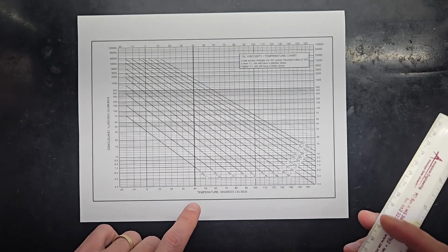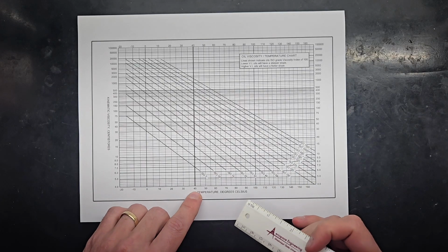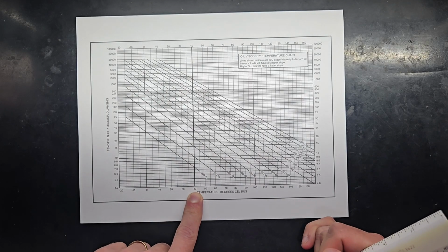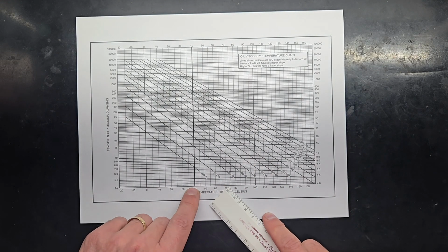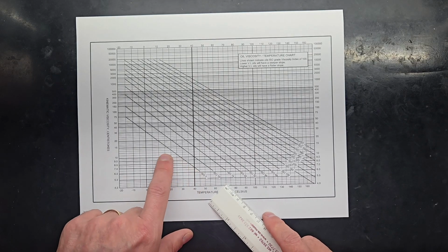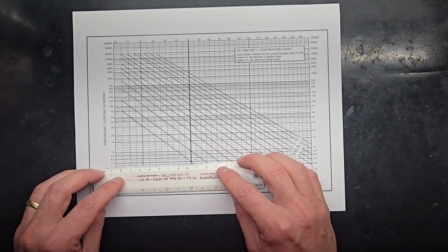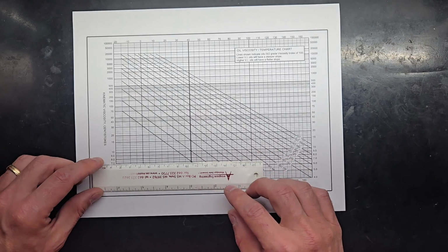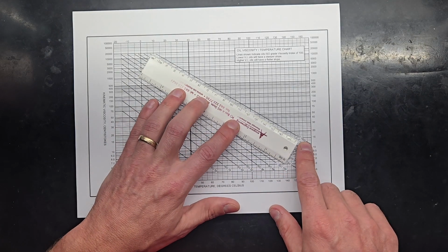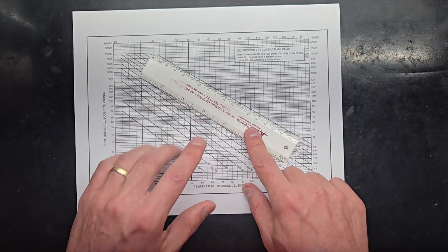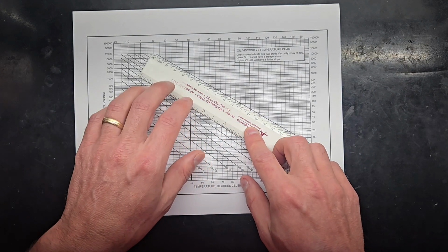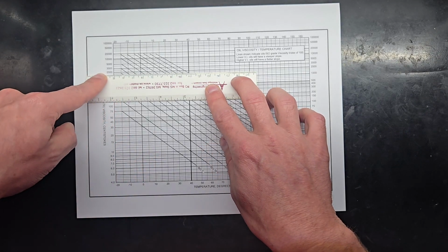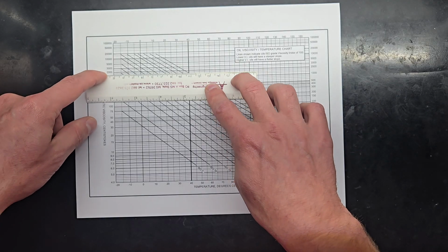And so earlier, remember I said for ISO viscosities, they're defined at 40 degrees Celsius. So we can follow this 40 line up, and where it hits our ISO 7, if we go across, lo and behold, it comes out at 7 centistokes. Again, if we go to our ISO 1500, we find our 40 centistoke line, see where it crosses, and again we have a viscosity of 1500 centistokes at 40 degrees C.